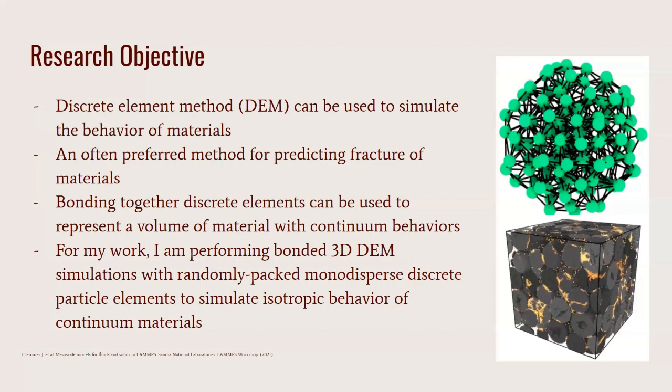In the randomly packed discrete domains of the study, I'm investigating the relationship of geometrical isotropy to mechanical isotropy, with also the random packing seed and the total number of particles. This is relatively unexplored in the literature for bonded DEM simulations of solid materials. With my research, I am working on characterizing the consistency of mechanical isotropy. Most bonded DEM simulations are done to understand the behavior of these models in the elastic regime, where geometrical isotropy is looked at very heavily.